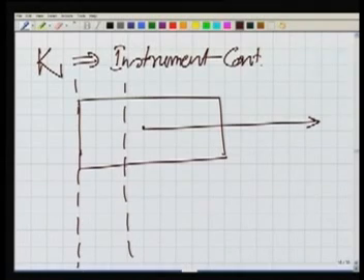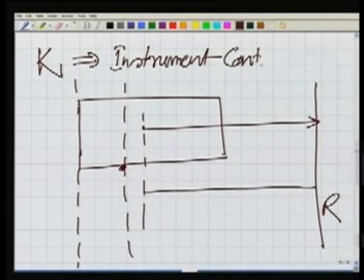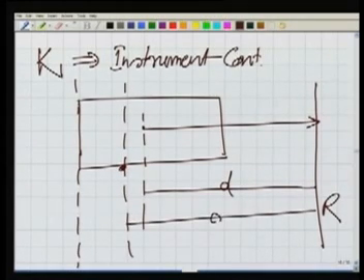For us, the center of the instrument is S. The physical center of the instrument is here. We are measuring the distances from here. So if that's our reflector, the wavelengths are actually being transmitted from this distance. So the distance which we measure is this, but the distance which we need is this.